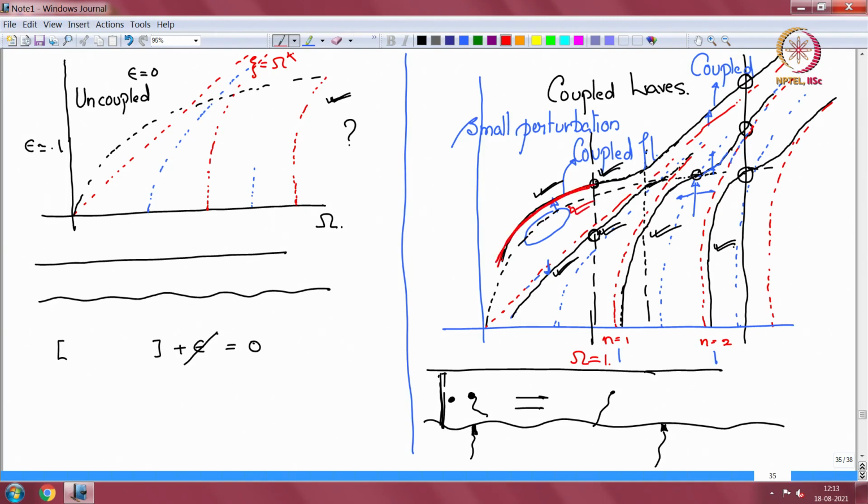So, this will be the coupled flexural wave below coincidence frequency. Above coincidence frequency there are frequencies where cot goes to 0, those are these frequencies. I will talk more about them. Below you will have a reduced value, above you will have an incremented value. So, this little portion is the coupled flexural wave.